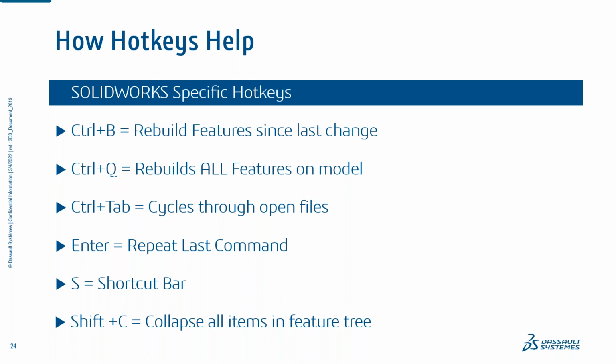There is a reverse of this. I'm not going to talk about it because people end up using it wrong, and it ends up slowing them down a lot because you can actually expand everything in the feature tree. So I tend to leave that one out. It's a more obscure command, so we're going to leave that one alone. But again, these are some of the specific ones that are a little bit more efficient.